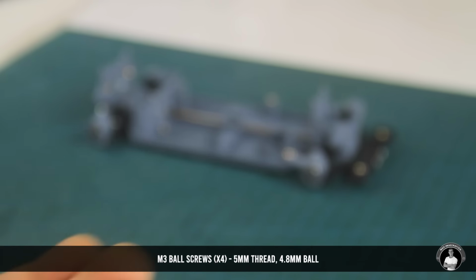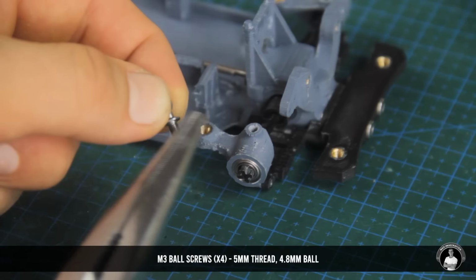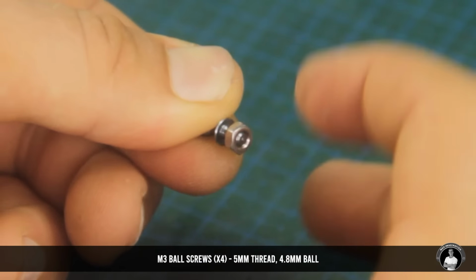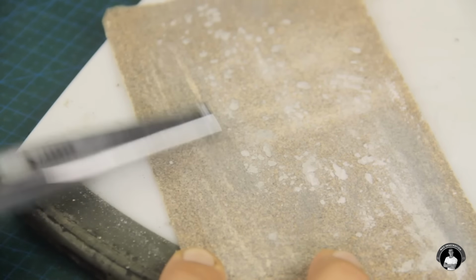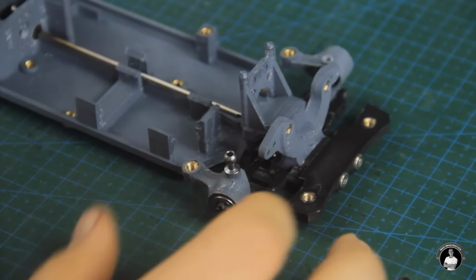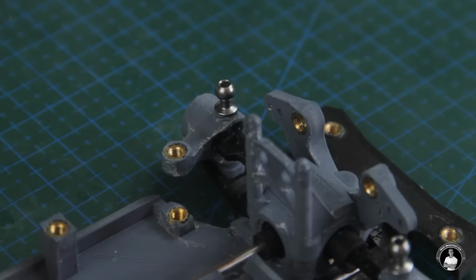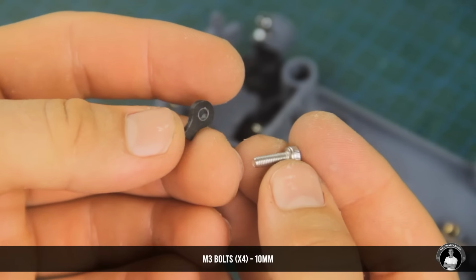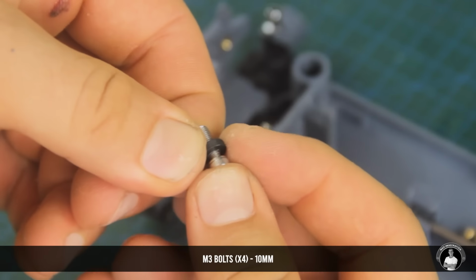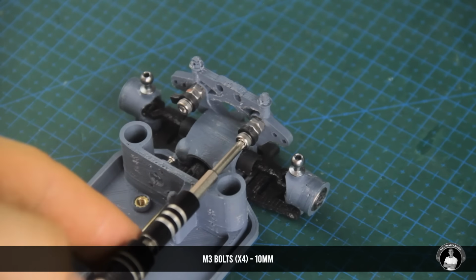To connect the upper swing arms of the wheel cups, we'll need 4 of these 4.8mm ball screws with their threads cut halfway up, sanded, and installed in the wheel cups while allowing the axles to spin. The upper part of the swing arm consists of an M3 bolt, swing arm piece, and a couple of nuts. 2 of these units screw into each of the gearbox housing arm pieces.